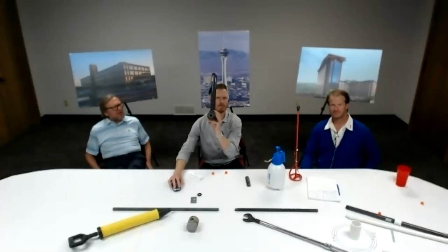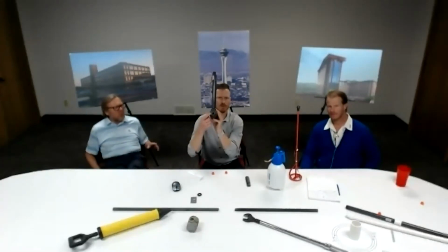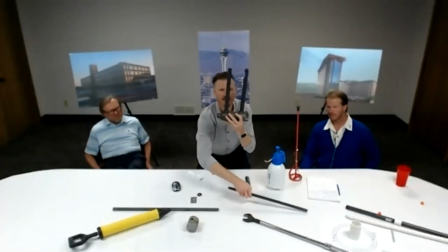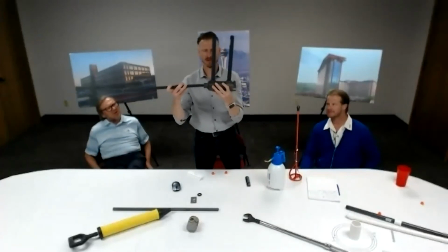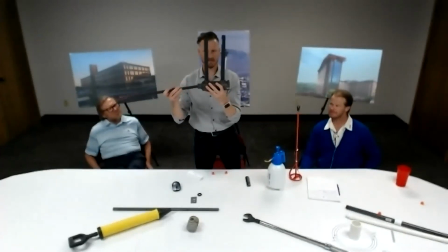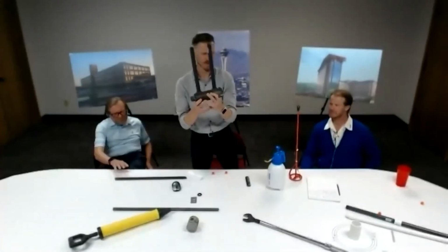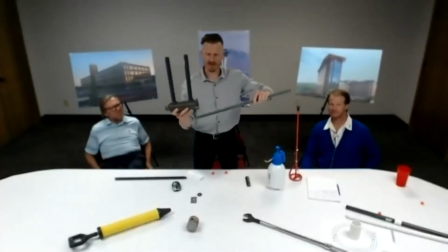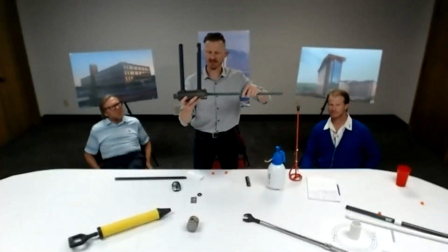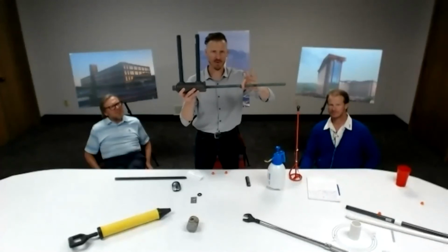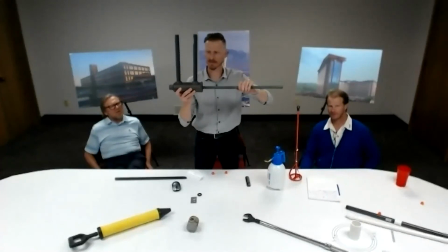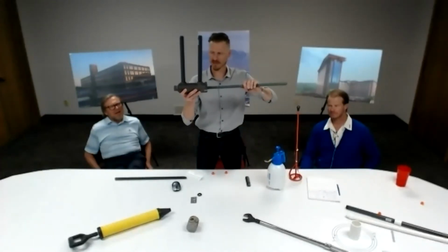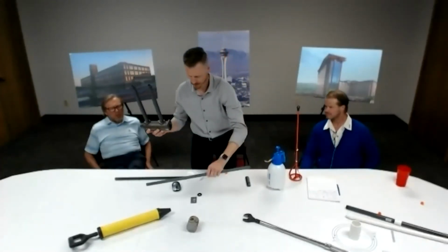It's really set up for precast. This one is a little different, and it has a hole that will just accommodate a number 7. So we have the threaded bar goes in here, pour side one, pour one, with your formwork back here. Then pour two is a loose bar that goes in, and actually there's a seat inside, so you know when it seats inside the coupler. And then when that shrinkage is occurring, it pulls out slightly, and there's very little play.